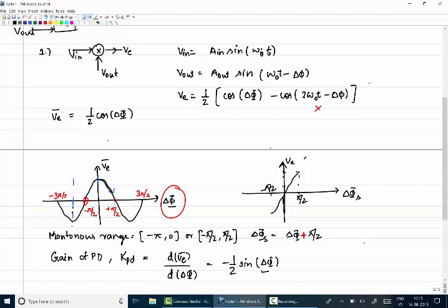This curve will just shift. Nothing more, it will just shift. So that's why I said that for a 0 frequency error between the two signals, V in and V out, for the phase error detector, if there is 0 frequency error to begin with, what phase error should it lock to in a steady state for a type 1 PLL?